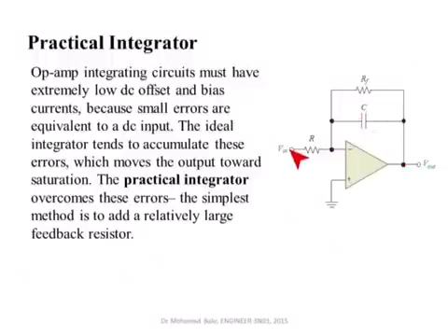So any voltage that you apply here will cause the negative terminal of the op-amp to be higher in voltage than the positive terminal, which is kept at 0. There is no feedback anymore. This means that the negative input can have a higher voltage than the positive, and that causes the output to saturate, and actually causes this capacitor to start to accumulate charges.